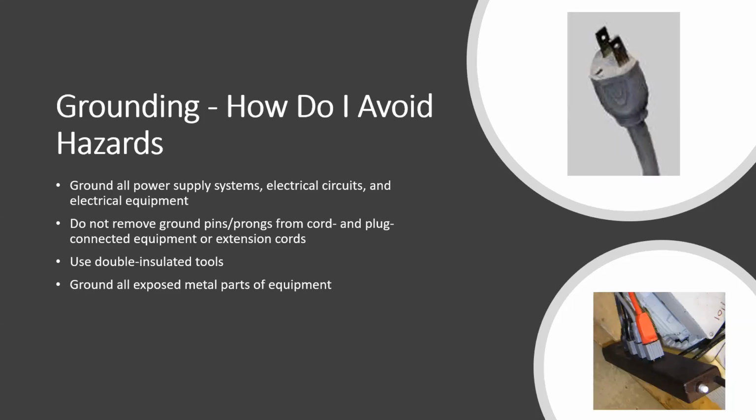Whenever there are electricity lines going underground, you will find that one foot before the main cable, Saudi Electricity has placed a yellow and black plastic tape, which is the indicator that there are electrical cables. So you can stop your excavation, or you need to take care while you are doing the excavation activities under the ground.